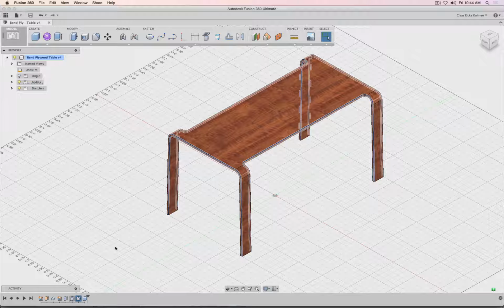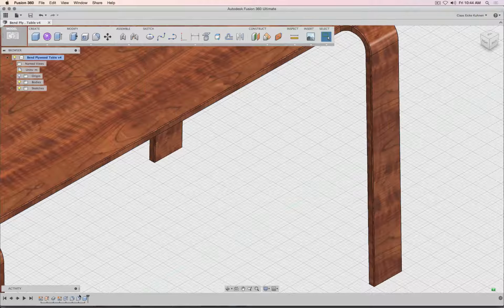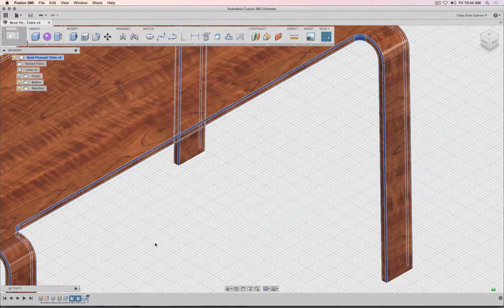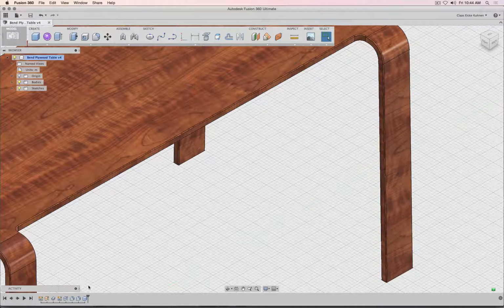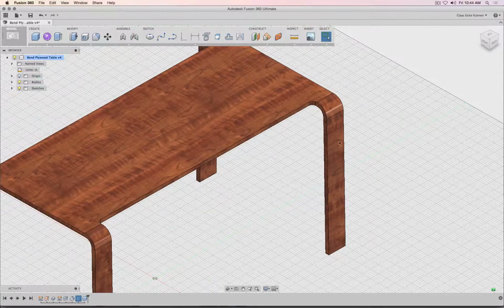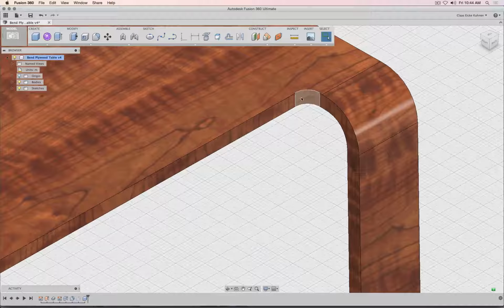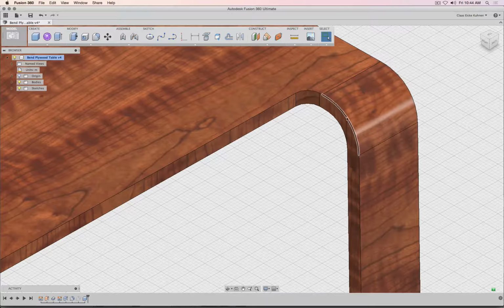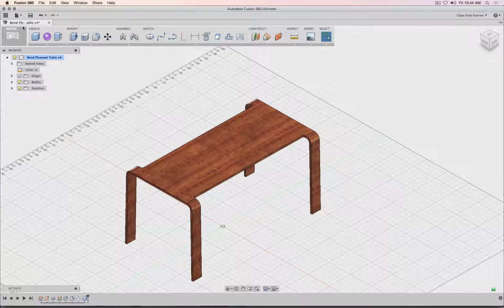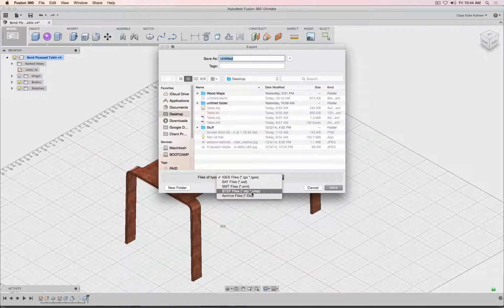Here are those fillets. So actually that fillet, and what about this? What does this fillet do? Oh, no, just, okay, you deactivate, so we suppress it. Okay, so this other fillet, that one I actually would like to keep because that creates this rounding, but just this hard edge, that one I would like to maintain. So export, step, and maybe let's call this one table 2.